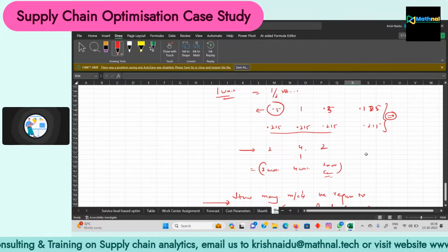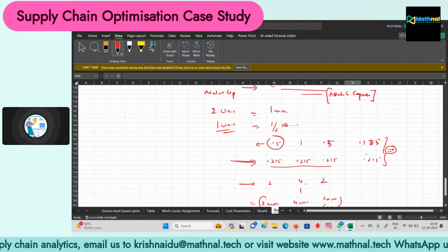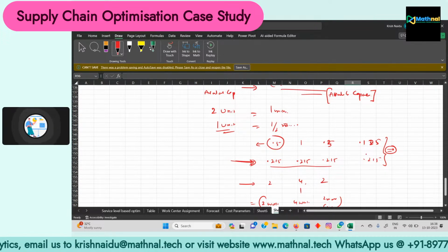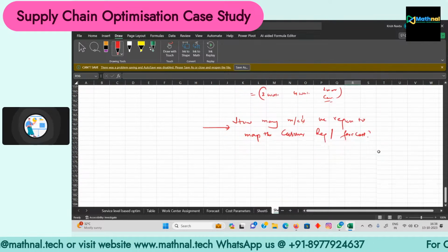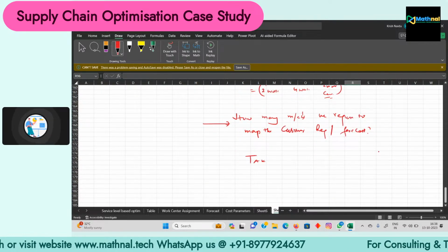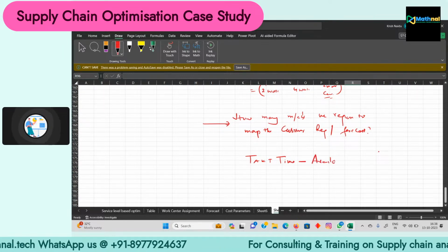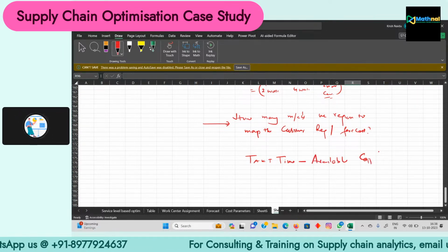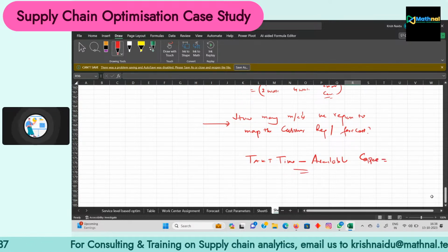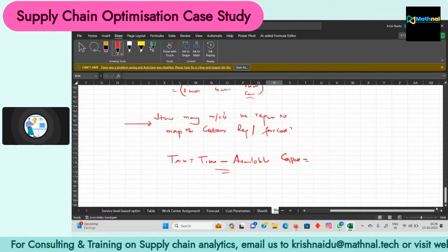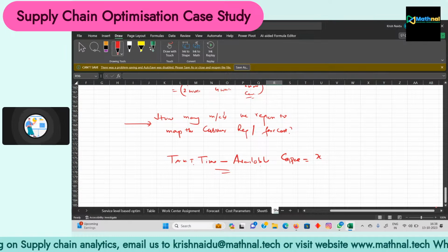That's why it's very, very important to have the measurement of the takt time and also the measurement of the available capacity. If you measure the gap between the takt time and the available capacity, takt time minus the available capacity, right? This measurement can be used to discover the number of machines required. Suppose the gap between takt time and available capacity is X1.